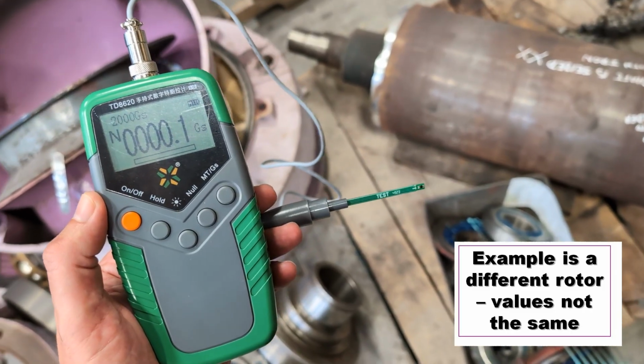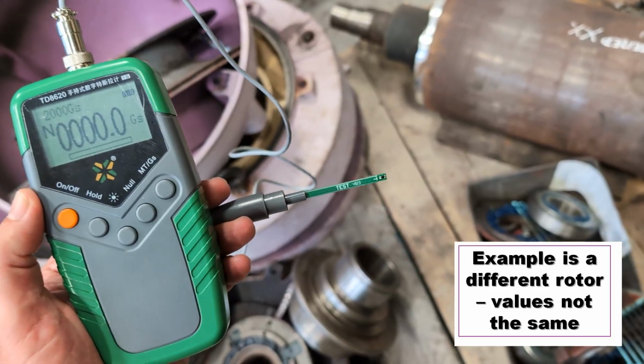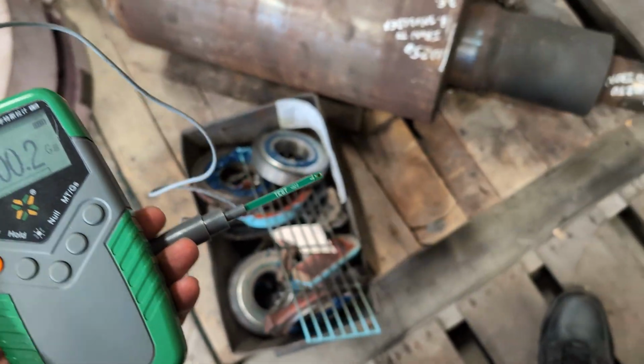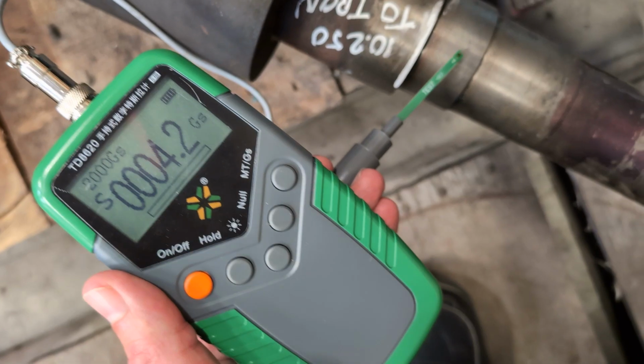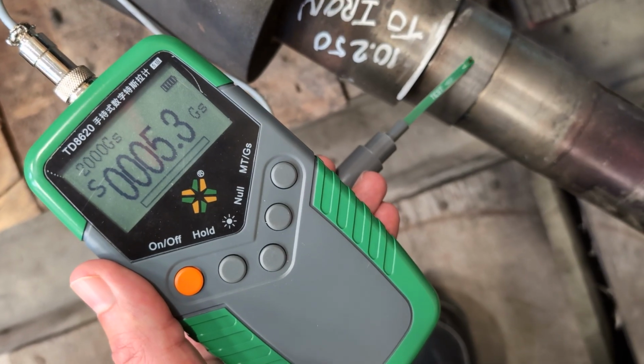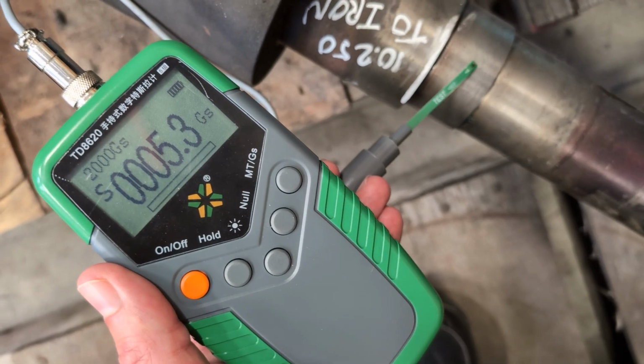So to measure the residual magnetism, I'm going to take off the probe end cover and expose the shaft. I'm going to go on the bearing journals. This is the drive end. Remember, because it's a radial probe, I want to go perpendicular to my measurement. Clearly it is more than 2. So I want to take a photograph of that and record it.